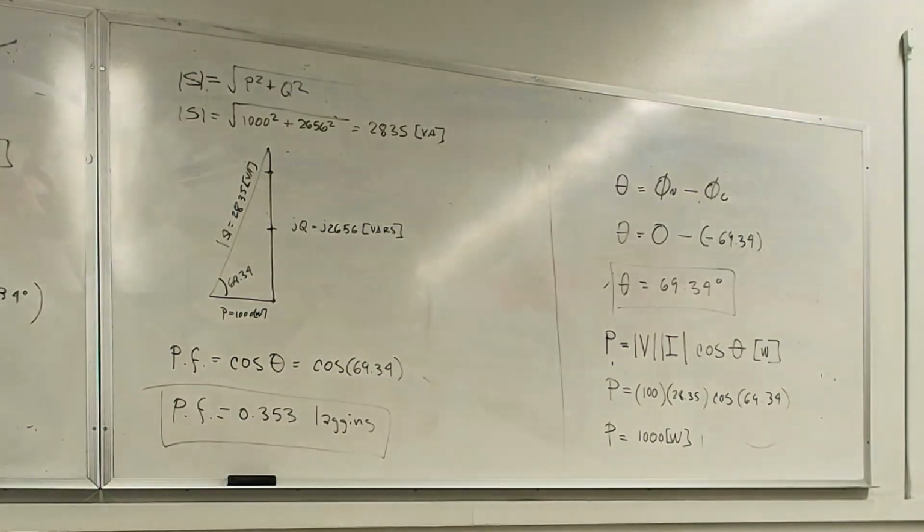You can have thousands of things hanging into that substation, but the core of the substation is the transformation. It's the transformers, and transformers consume a lot of vars. Those are inductive, right? Right, because they're big inductors. So that's why you put capacitors inside the substation to improve the power factor of the substation. Basically, what you're doing is providing the vars that the transformer needs so that it doesn't come from the generators or the sources, right?